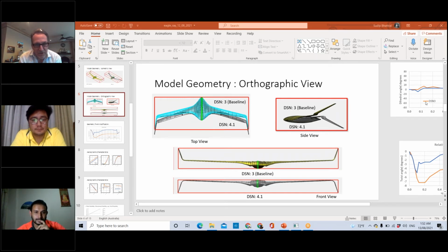One thing that's for sure, at the point of liftoff, since you can adjust the pitch attitude, you might not change the airspeed for liftoff, VLO. You might not change VLO, but it will allow the airplane to continue to rotate faster after liftoff, having the wheels further forward. If they're that far back, it's going to inhibit the rotation at liftoff.